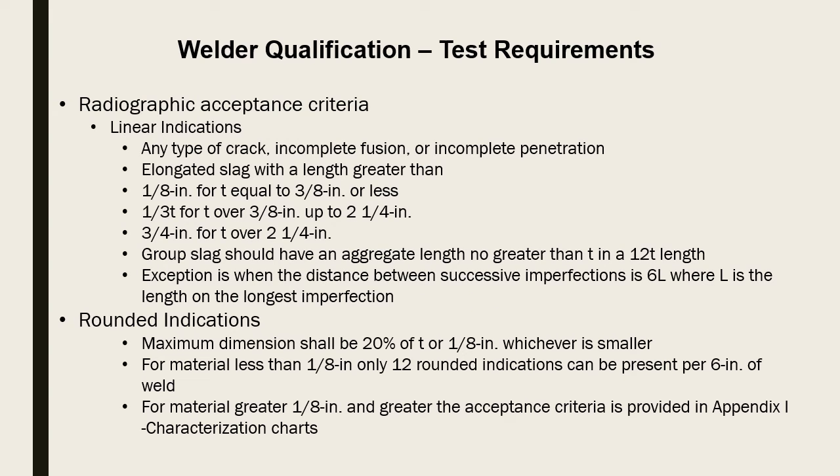Welder qualification test requirements. I'm not going to go through this. This gives you a general idea of what the acceptance criteria are for radiographic testing. You can't have any slag, elongated slag over certain lengths, or grouped slag, or whatever. Here's all the criteria. You can see it's fairly involved.